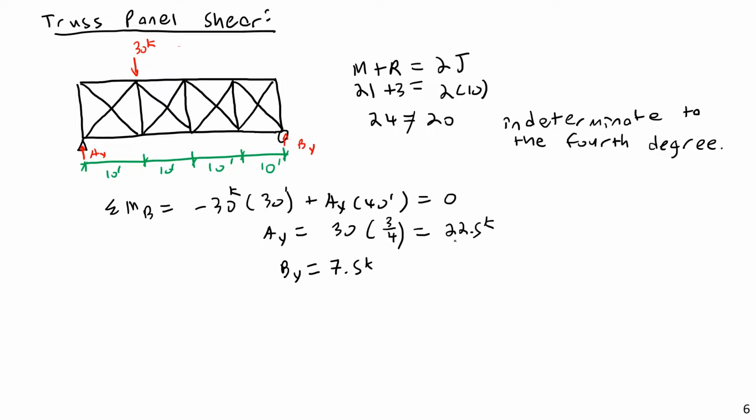Unfortunately, I have way too many members in order to actually solve for the forces in all the members. So let us look at how I would handle this. I'm going to use the same problem to illustrate how I would handle this depending on whether the braces are slender or not slender. So, let us assume first that the braces are slender.